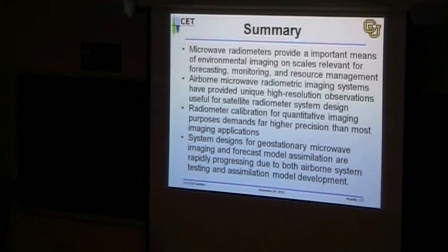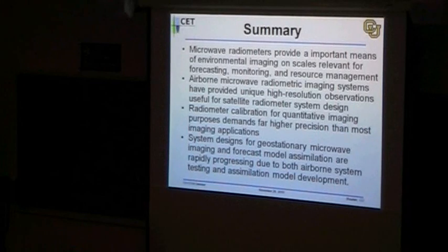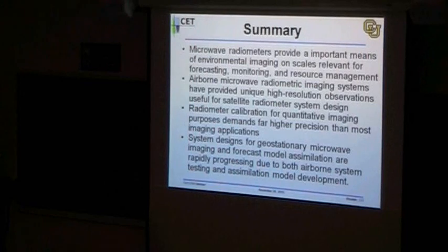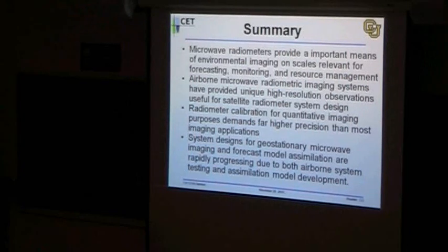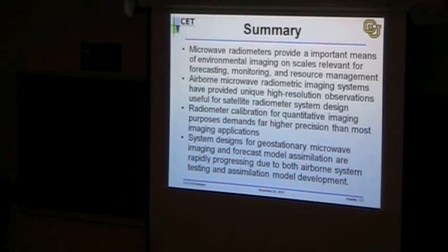But we are finding more and more that the anthropogenic signals that are being emitted by a host of sources, whether they be computers that are operating out of band that may not be sealed properly, whether they be cellular phone systems that have harmonics, or whether they be even legal transmissions that just are encroaching because of social and economic pressures on the open bands. We're finding that's becoming a very significant problem below 10 gigahertz and is even being noted at frequencies around 18 and 20 gigahertz in the current satellite records.